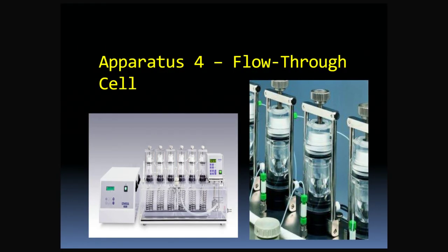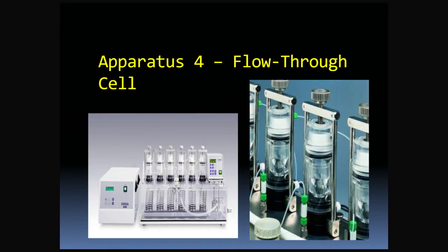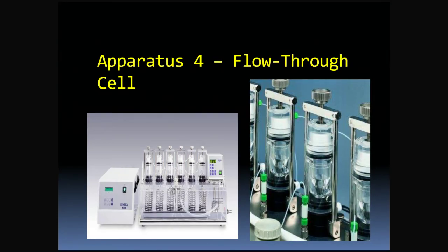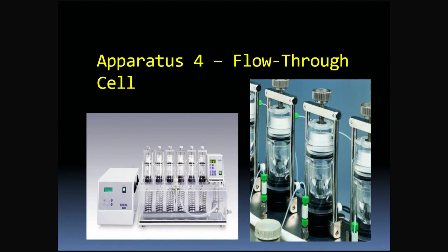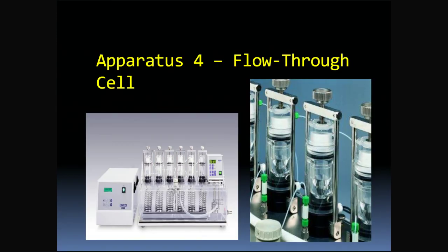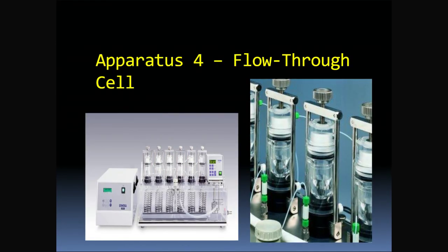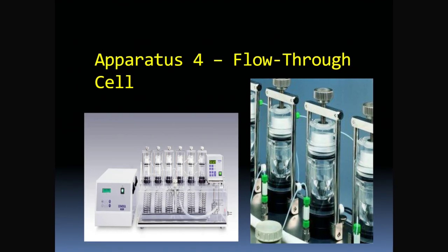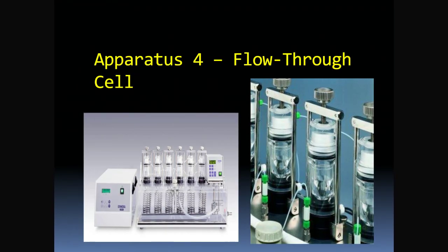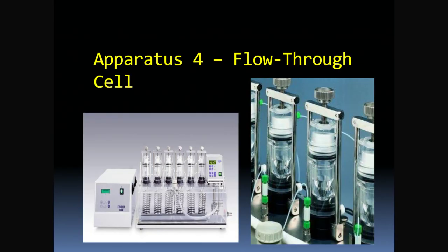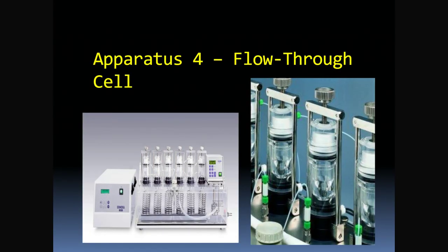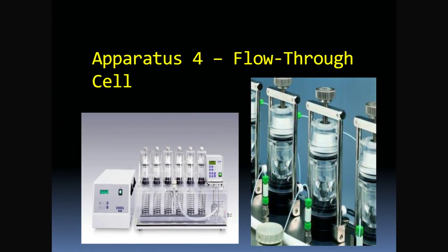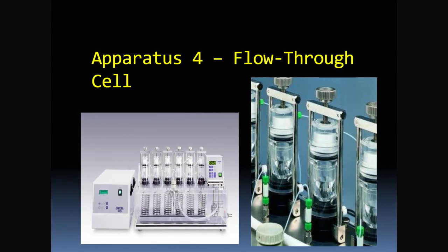By utilizing an open-loop configuration, we effectively decouple the dissolution rate from the bulk concentration, ensuring that the concentration gradient, the mathematical difference between the saturation solubility and the current fluid concentration, remains at a theoretical maximum throughout the entire assay. This constant renewal of the liquid phase ensures that we are measuring the intrinsic rate of molecular detachment without the inhibitory effects of local saturation that plague static vessel designs.